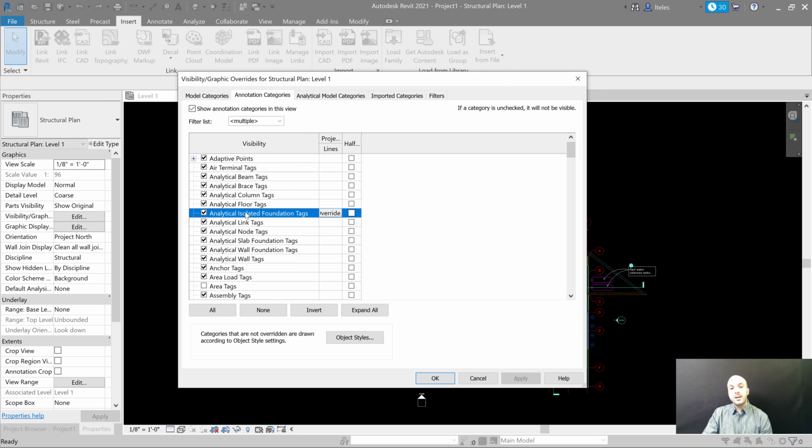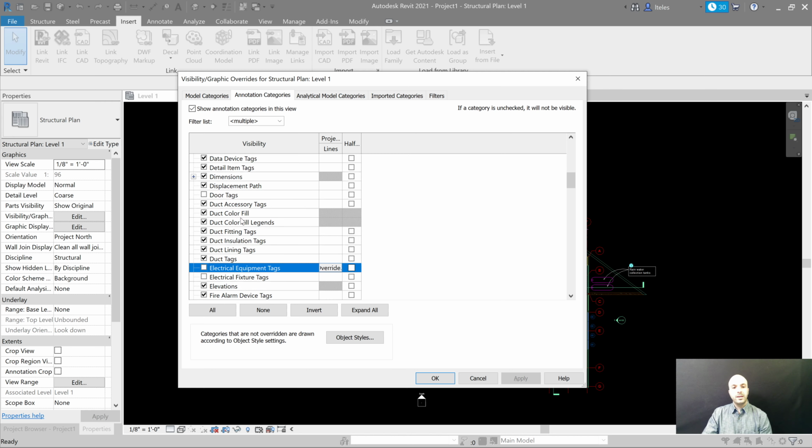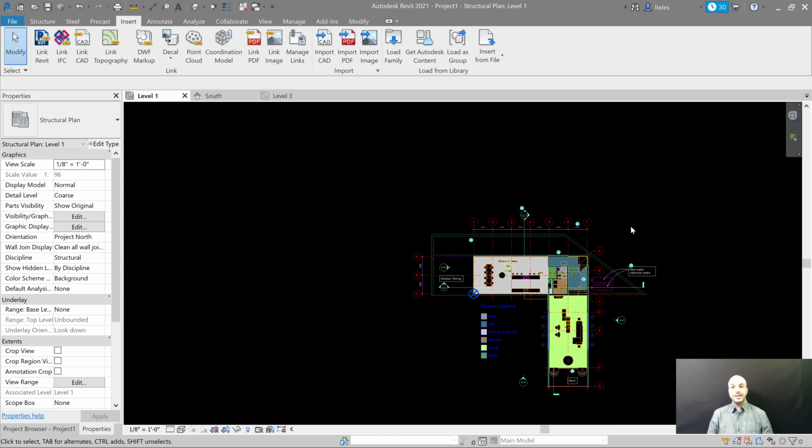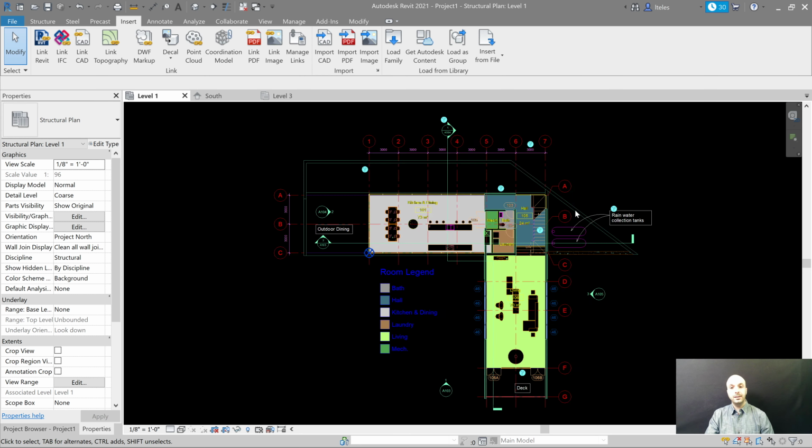If you select any title and now type in EL, it'll shortcut and take you straight to the place where you want to go. So let's click on elevations and uncheck, and they hide. Now if you were to retype on your keyboard ZE, now only your CAD background zoom extends, right? ZE, it zoom extends to this window, okay?